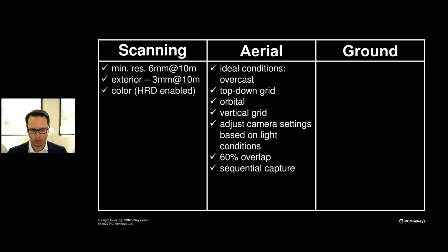And then, have 60% overlap. The higher the better. It's the same as doing a cloud-to-cloud registration. And then the last one, make sure you do a sequential capture. This is gonna make your life easier when you have to align those photos in your application.